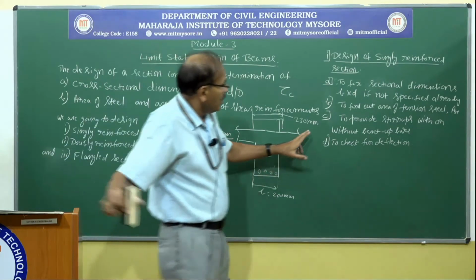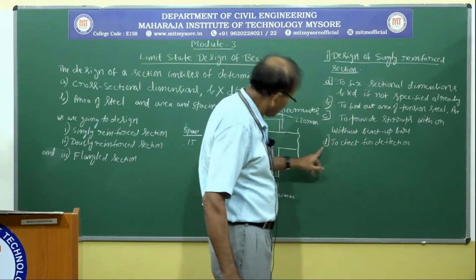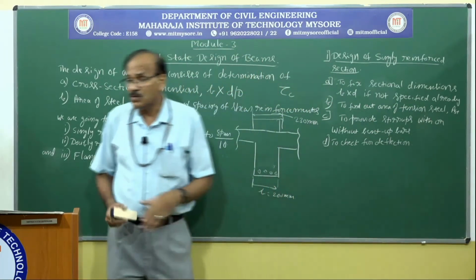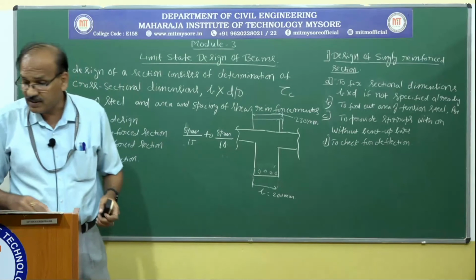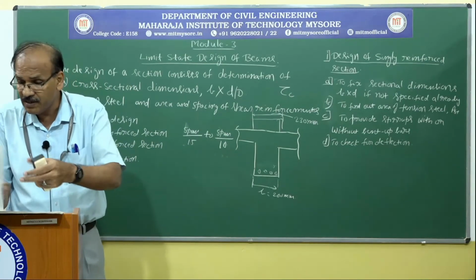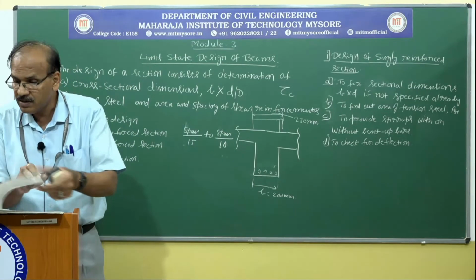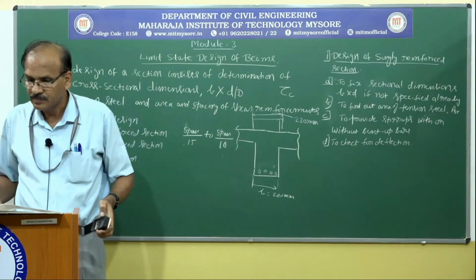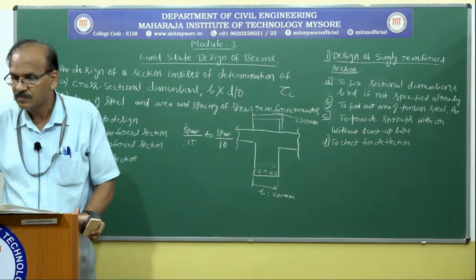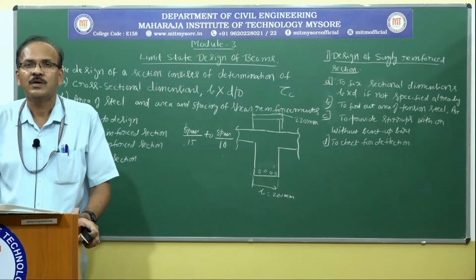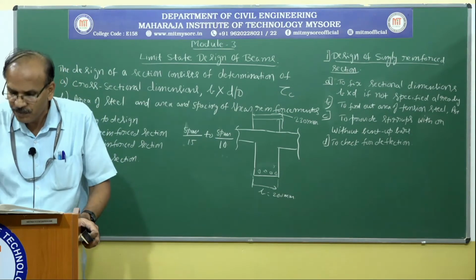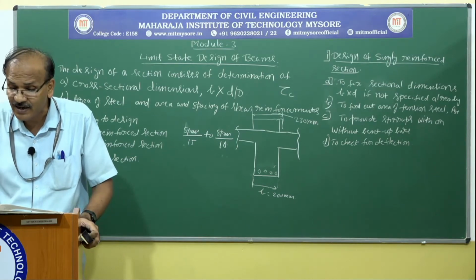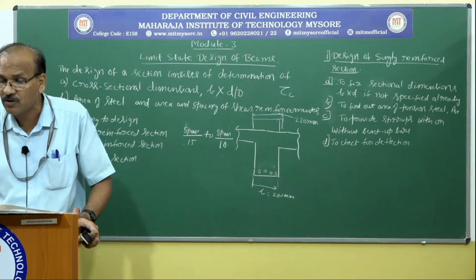Next, after this, we are going to check for deflection. To check for deflection, please go to page number 37 of the code book. I hope you are on page number 37. In the first column at the end, it says 23.2 control of deflection.